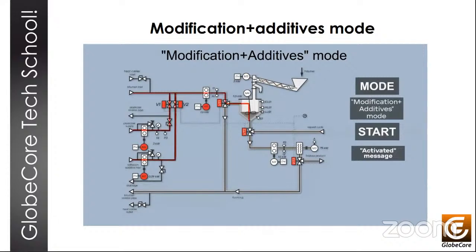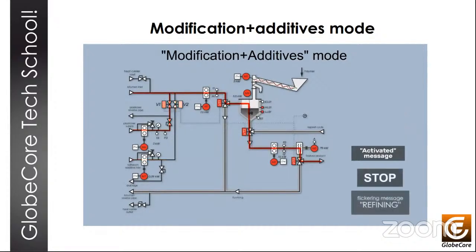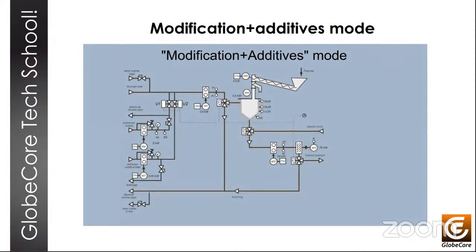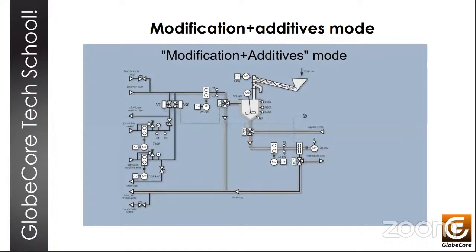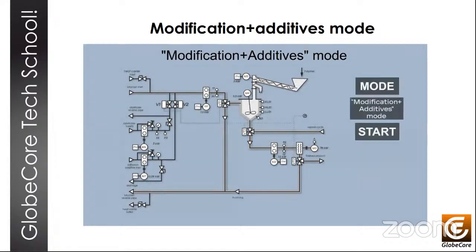If the stop button is pressed during operation, the unit enters the finishing mode. A blinking finish message will appear on the controller screen. What that entails is the M1 pump stops, the VT1 three-way valve switches to the position of supply of bitumen to the return line, the M5 screw conveyor turns off, but the M3 mill, the M4 mixer, and the M2 pump still continue to run.